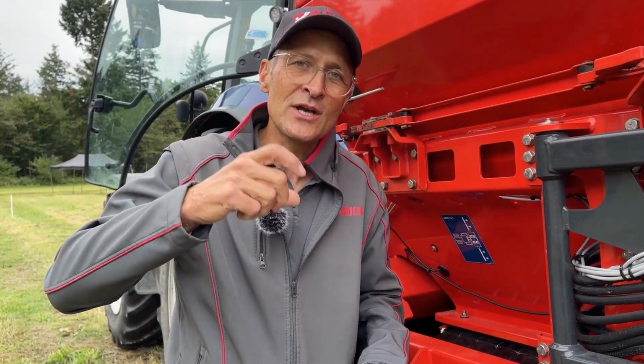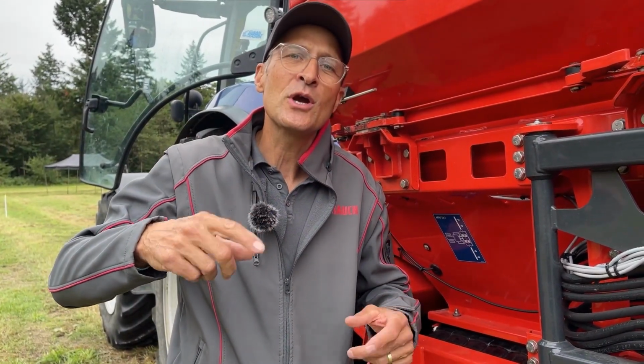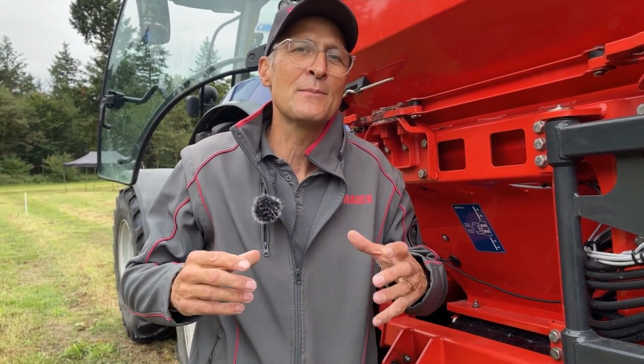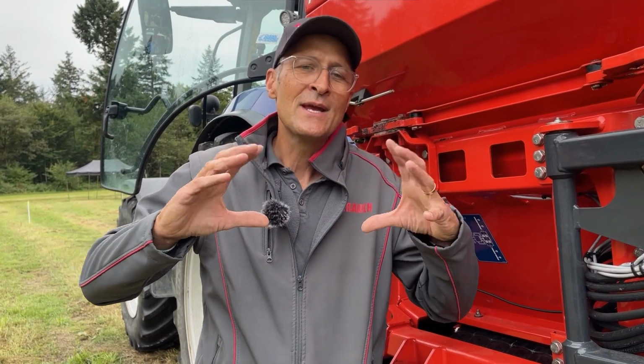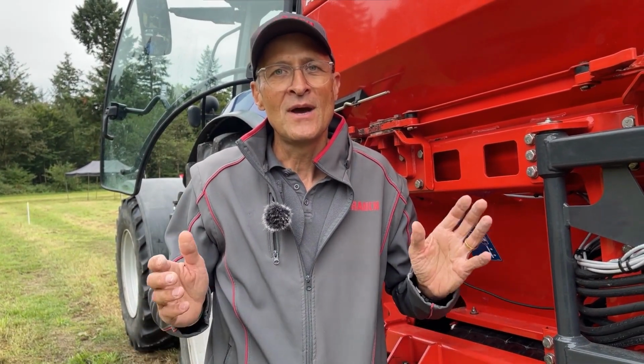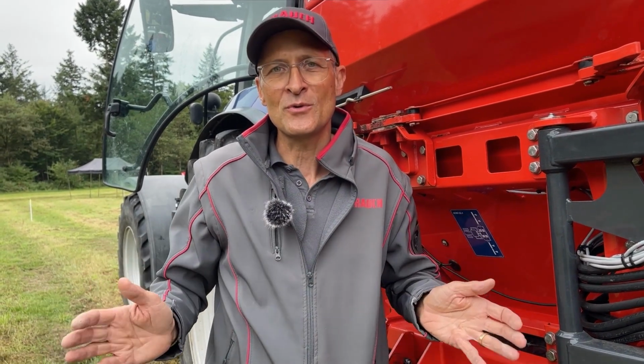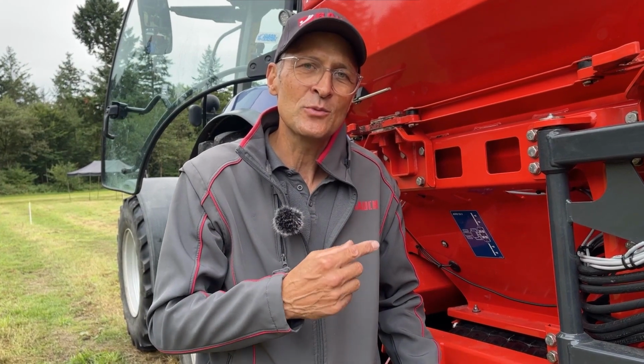And it gets even better. Not only can we switch each nozzle individually, but we can also adjust the quantity. So for example, when you are spreading using an application map, I can spread a different amount for every 20 meters, and this allows me to apply application maps with a fine grid, for example 5 by 5 meters or something like that, with super precise accuracy, and that's the level of precision in fertilization that we need. All right, I'll unfold it now and then we'll take a closer look.